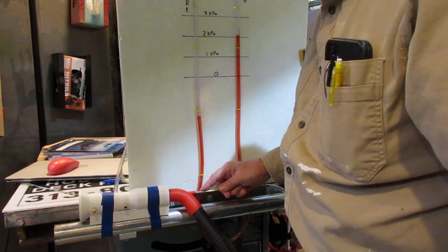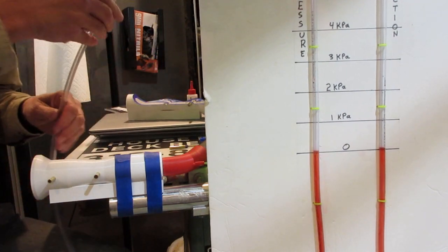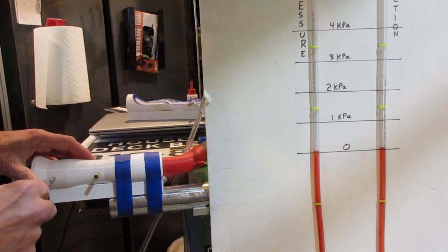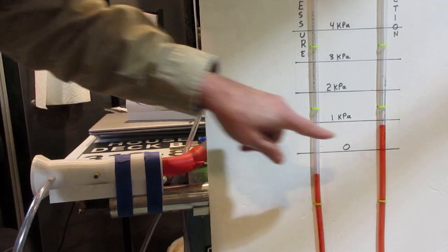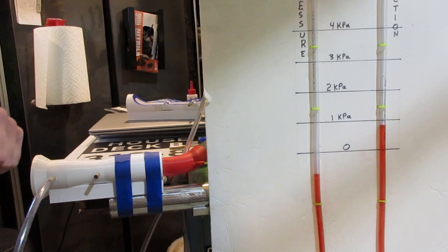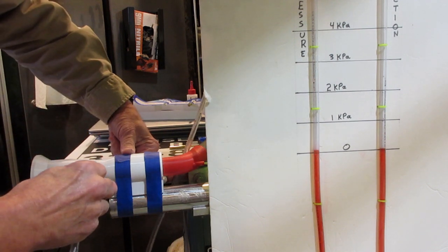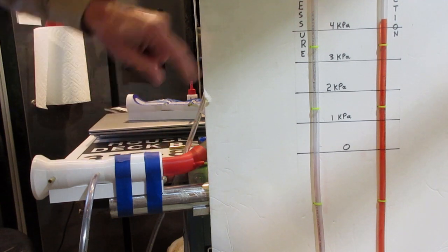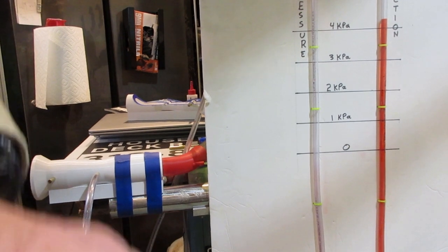Looking at the static pressure, or the pressure on the walls of the Venturi, we'll start by looking at the upstream port, and that is going to show a little bit of suction because we've accelerated the air into the Venturi from our surrounding atmosphere. And we go down to the narrow part or throat of the Venturi, and you'll see a little over 4 kilopascals of suction there, or low pressure. Again, in accordance with Bernoulli, right? This is what Bernoulli predicts, along with conservation of mass.